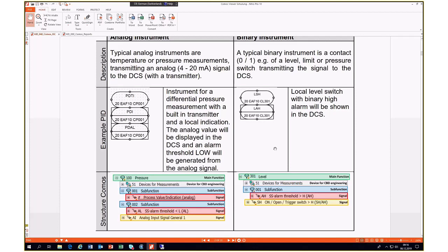We actually go a step further now with COMOS. In the last couple of years, we've developed this. So we're actually doing the cabling. And in order to do the cabling, we need this object, number 51. So you don't really have to do anything with it, but you just have to not delete it. Make sure it's still there, right? So that's the reason this is here. Normally it's always there.